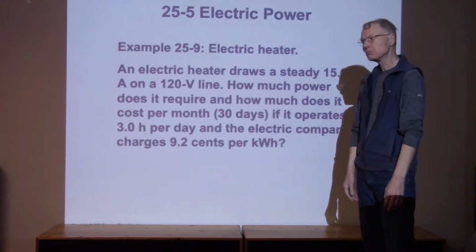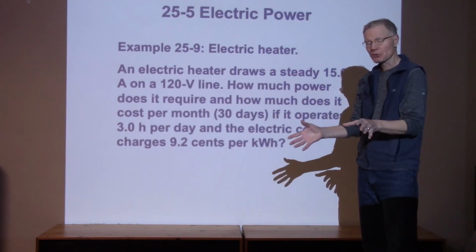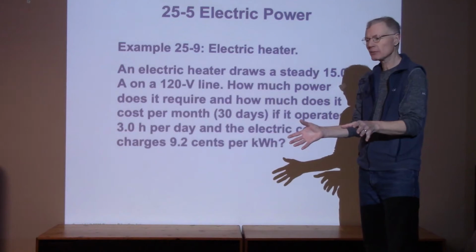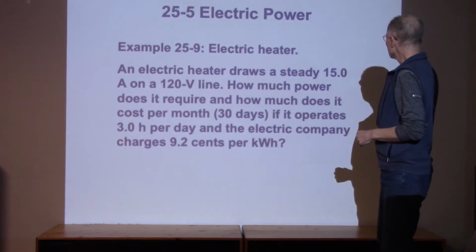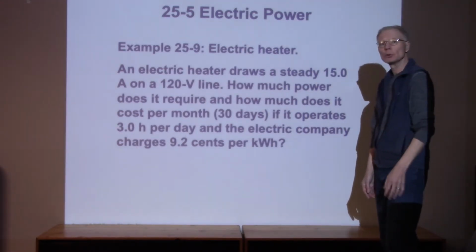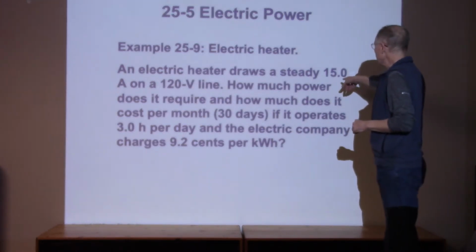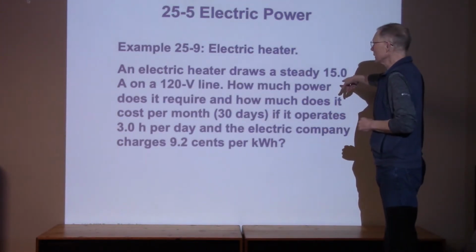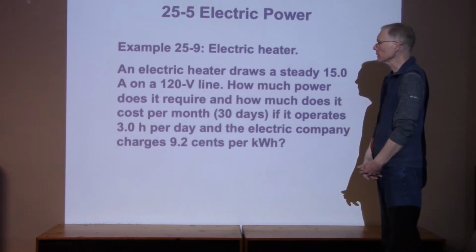There were quite a few sections where the insulation was falling off. So over the next few years, I ended up rewiring the whole house and putting in 12 gauge wire, which has a diameter of about 2 millimeters and is rated at higher than 20 amps, but still the circuit breakers for each line in the house are at 20 amps.